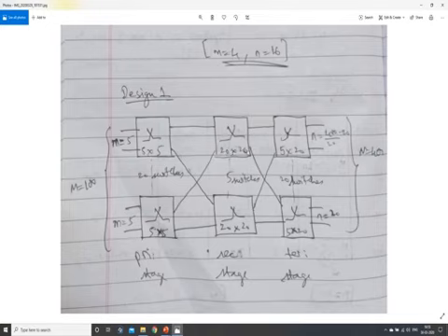Now since the number of outlets for the secondary stage is specified as 25, what does this indicate? This indicates that there will be 25 tertiary switches. Now if we have 25 tertiary switches, I have to divide it among the 400 outgoing trunks. So what will be the number of outlets present for each of these? In this case it will be 400 divided by 25, which turns out to be 16. So if I consider m is equal to 4, I get the number of outlets equal to 16.